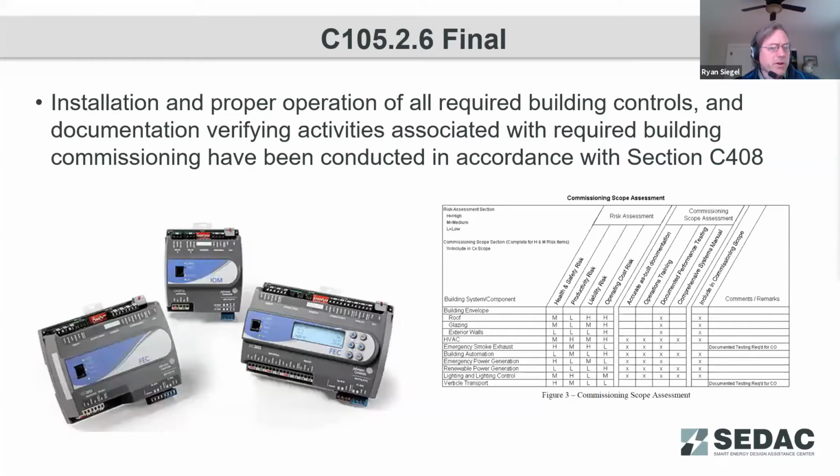So with our final inspections, this is covering anything and everything that may not have been captured earlier. So this may be a second capture for the commissioning of the HVAC systems. Generally during mechanical inspections, there may be the preliminary report of commissioning, which may be more of the functional performance testing phase, just saying, is everything working?